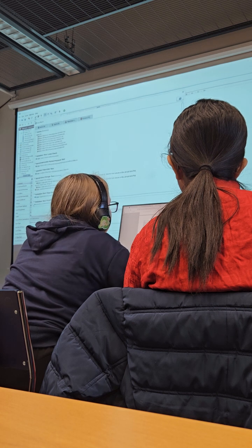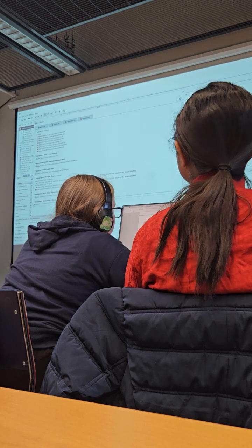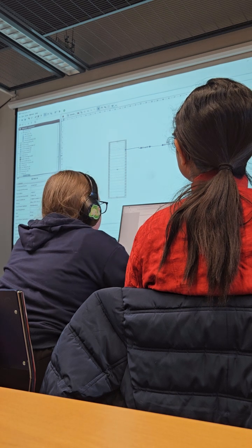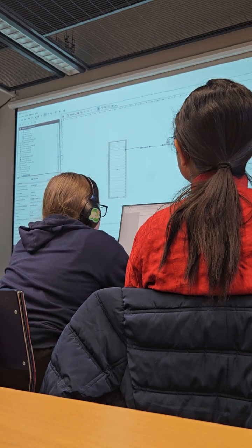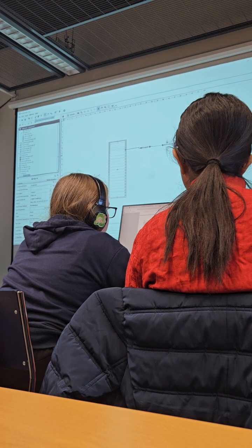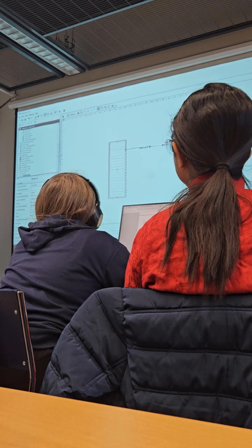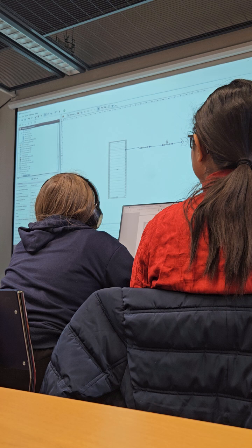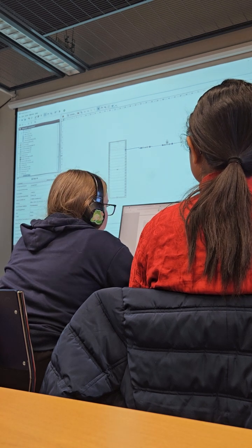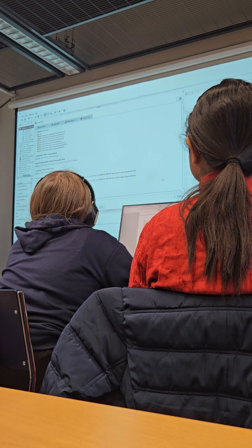What I just did is that I clicked here this red check all components in the model, so it checks if everything is given, if all the initial values have been given and so on, and then it gives me a list of possible errors.